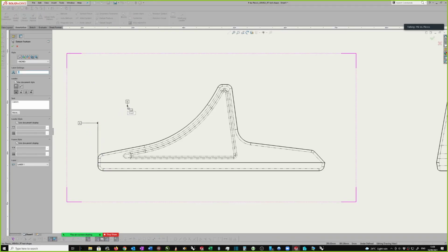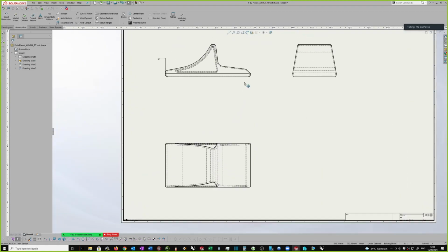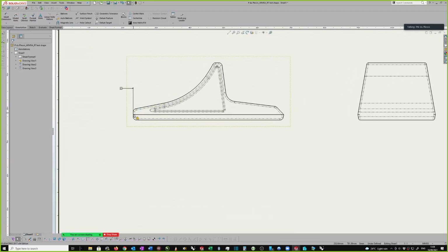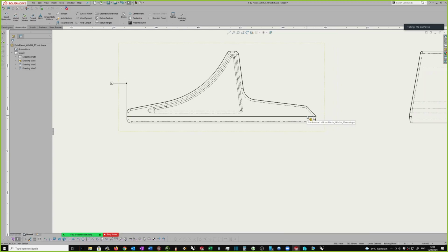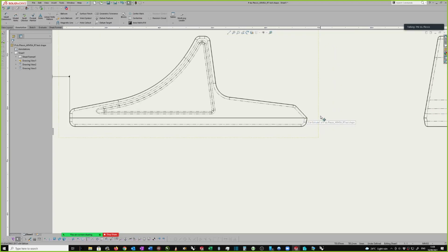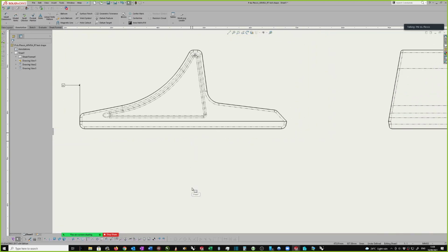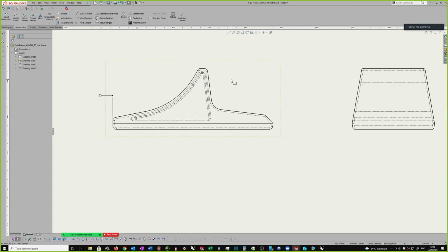Okay, so that's a legitimate datum. We would have put in center lines. I'm not going to worry for now. So that'll be your datum. That's because this is a nice flat face. You can see the way I've designed this. It's actually got a split line here. It meets at a sharp point because it's going to demold in that direction down and that direction up, and then this piece here I'd either have to put tapers in to get it out, or it would be a separate part in the mold which comes out on the sides.